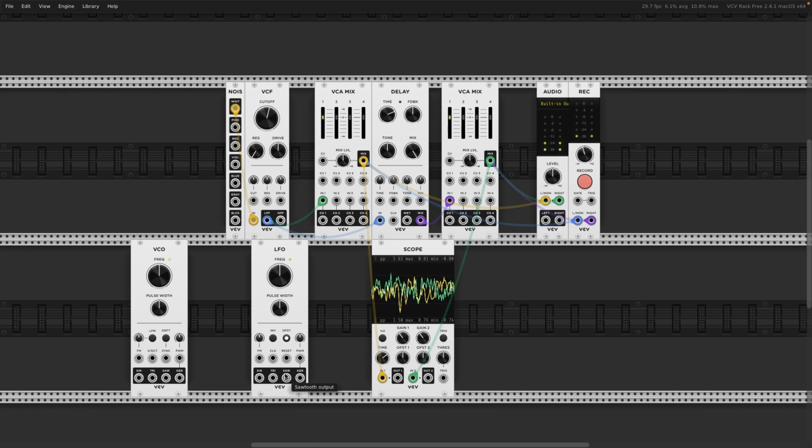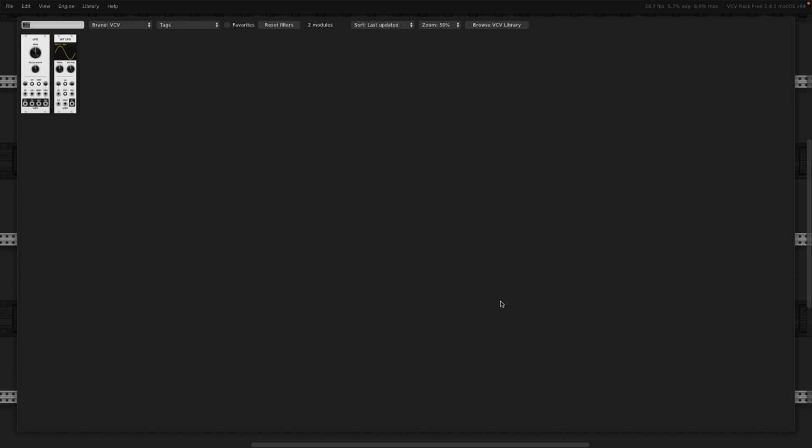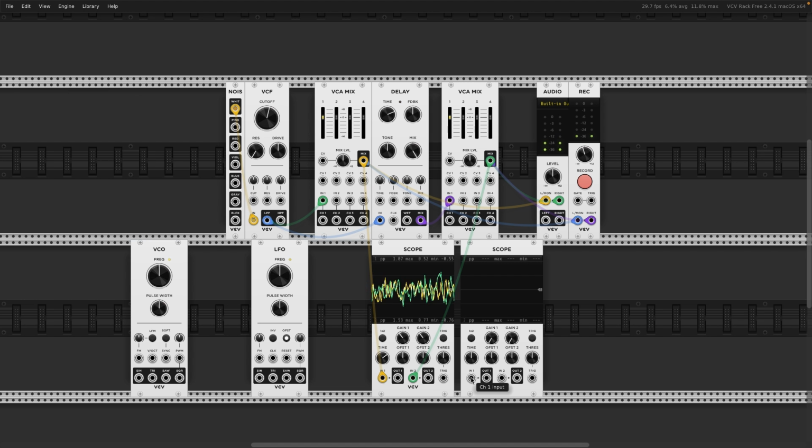And here we have various outputs, so you can move this knob up and down smoothly. Then you would use a sine wave, or if you use a sawtooth wave, let's visualize that too. Let's get another scope, because we need another input. And now let's see this LFO. So we have the sine wave here. So this is very fast, so let's turn down the frequency.